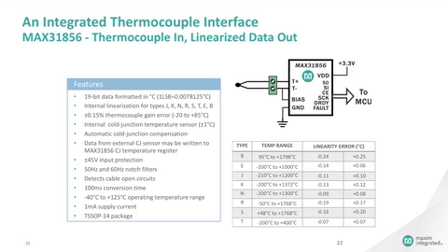It can interface to 8 different thermocouple types, while the MAX31855 required a different IC when changing from one thermocouple type to another. This device also handles the linearization internally, relieving the microcontroller of that burden. Accuracy is improved and is roughly 2 times better than the MAX31855.